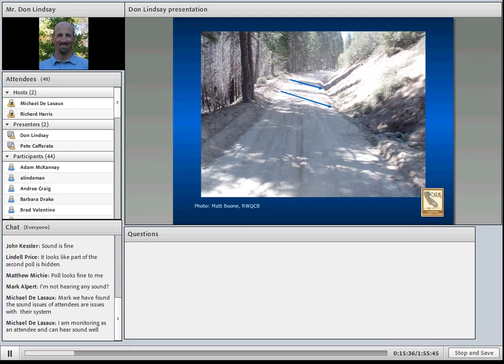However, inboard roads are susceptible to storm damage due to the inlet of cross drains being plugged and the failure of tall cut banks. In addition, inboard roads can have a large footprint and are expensive to construct and maintain.